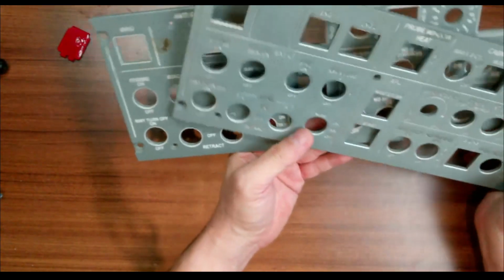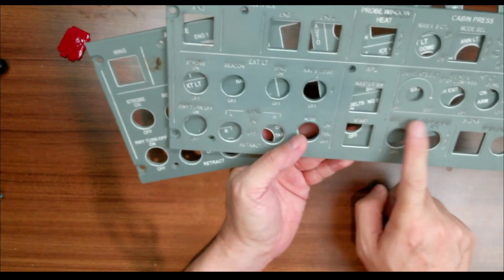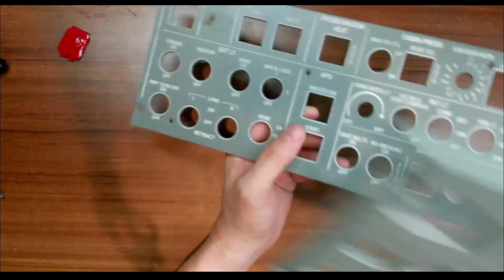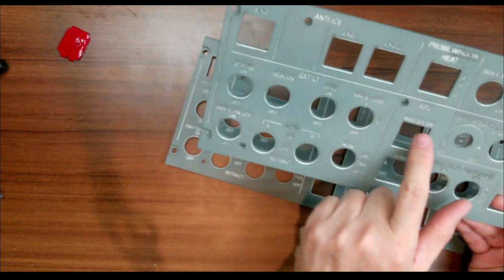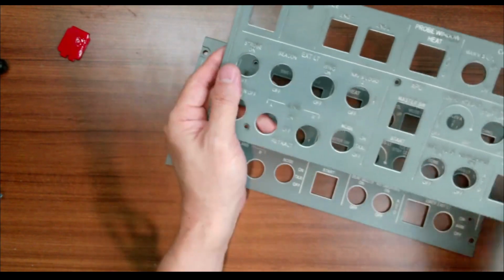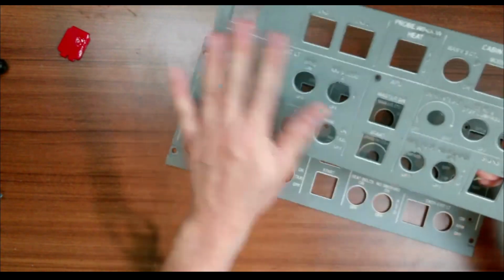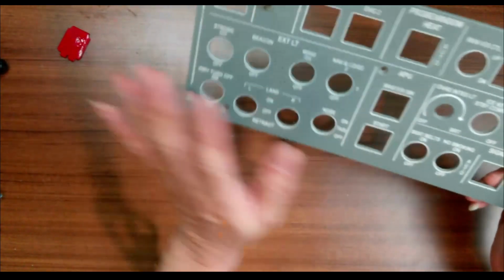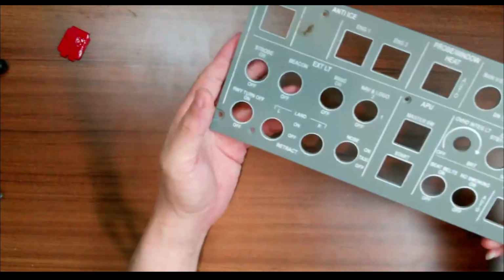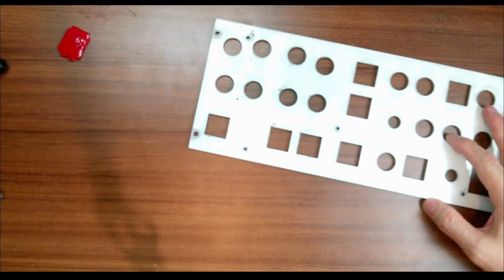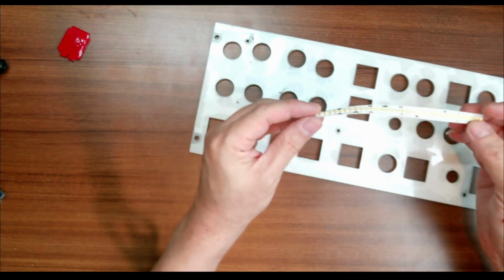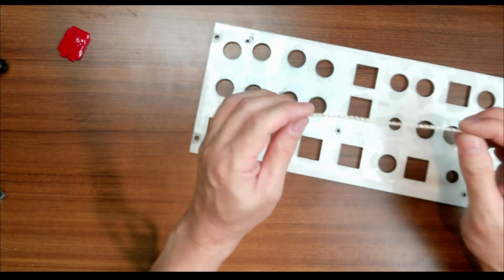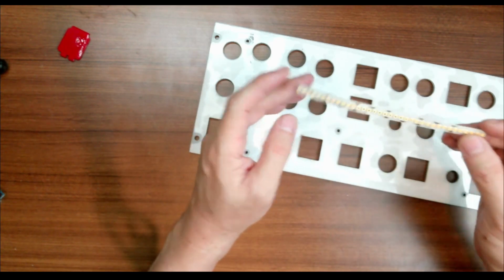This one is a failed one, where I wasn't able to engrave properly. It blurred the letters. I think it's too much power that I used here, so it dug in too deep when engraving, and it looks very bad. This one is a much better one, but the installed one is even better. This one is just an example, and for the LED strip, you can use a dense one, like 240 LEDs per meter, or 120 LEDs per meter should be sufficient.